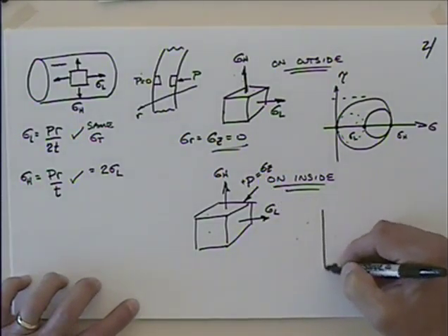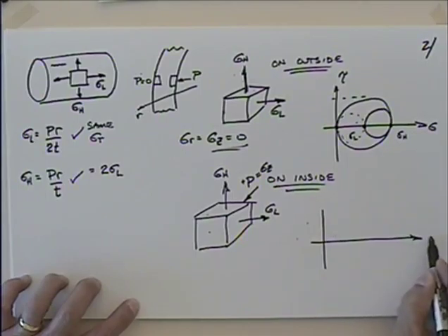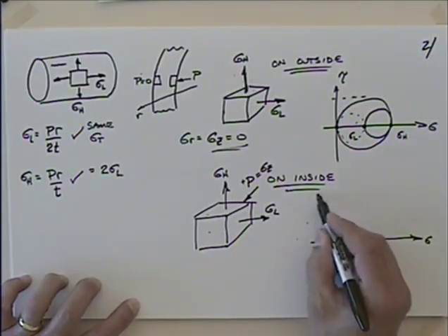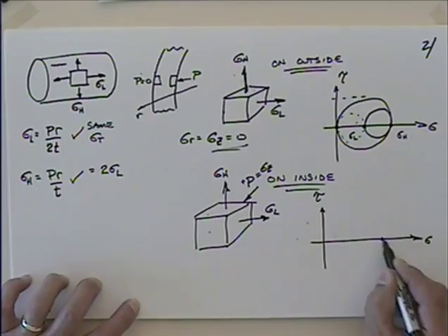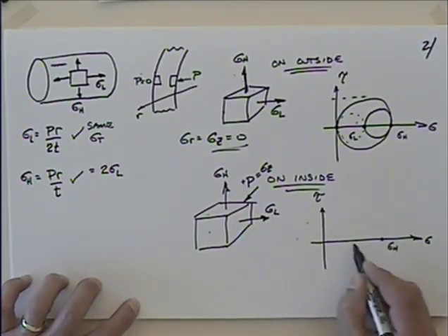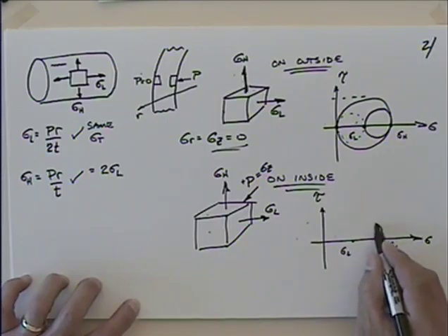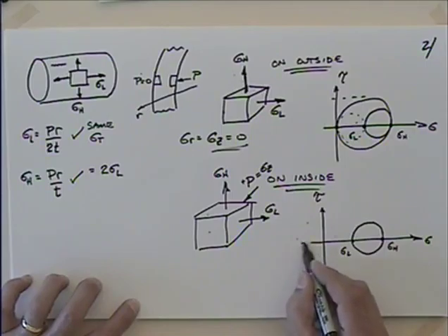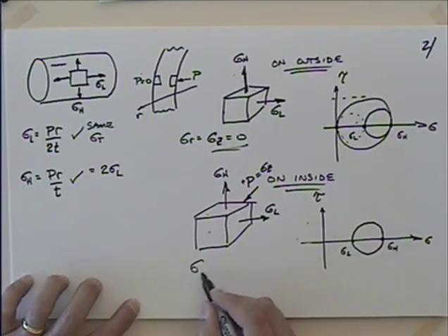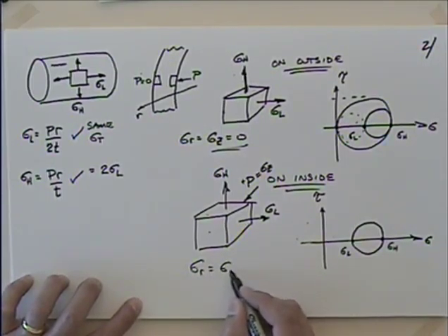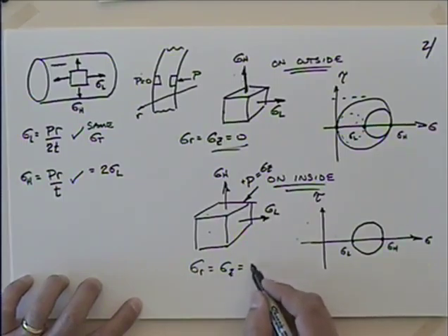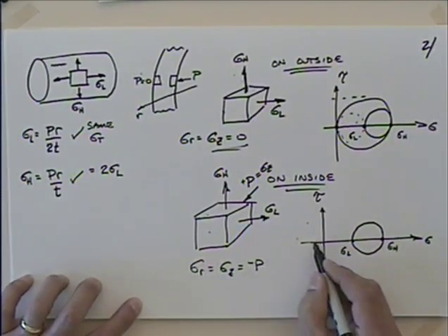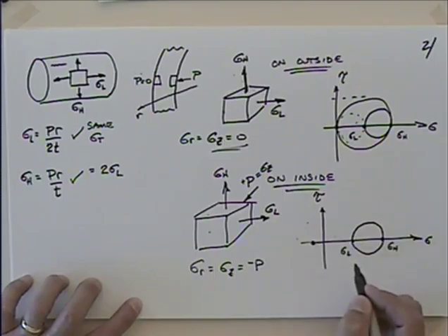So when I plot this on Mohr's circle, again I have the hoop value out there, sigma h, and the longitudinal value, sigma l, and the circle that generates. And now if I look at the z direction, where we have a sigma r or sigma z, that's equal to minus p, isn't it? It's in compression. And that's a little awkward, right?